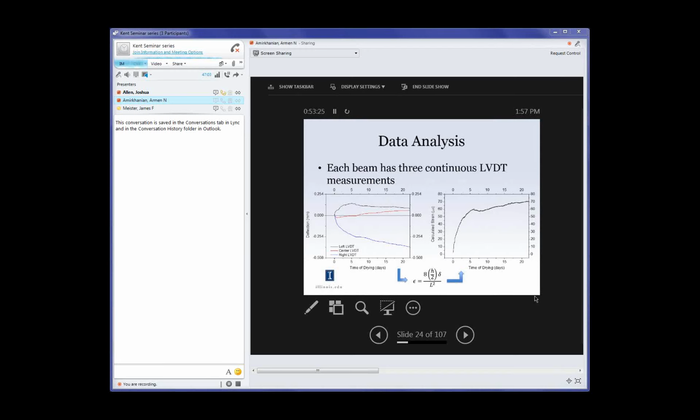Obviously, yeah. And going back to the LVDTs moving like that, I put, I think it was 15, of these spring-loaded LVDTs on one beam. So they do have some minute amount of force on them, and the marble bed that these beams sit on is pretty frictionless. It takes barely any force to move the beam. So I put 15 spring-loaded LVDTs on one beam to see how many LVDTs were needed to actually move the beam. It took about, I think, 9 LVDTs worth of spring force to cause the beam to move.